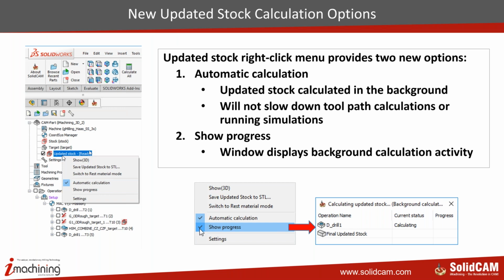Another very important thing is that once you drag and drop this icon and see the updated stock condition, you can always save this updated stock as an STL file, and import this STL file as the initial stock for any other setup or any other CAM project.